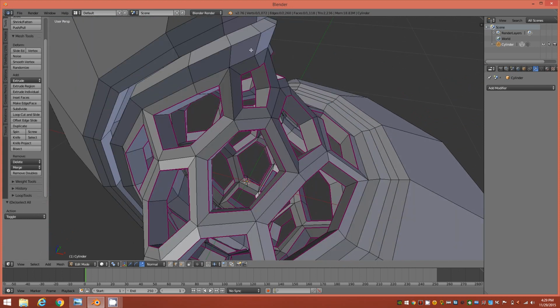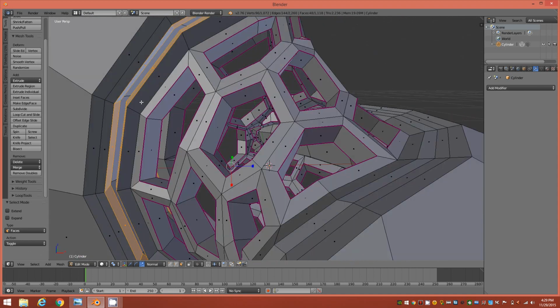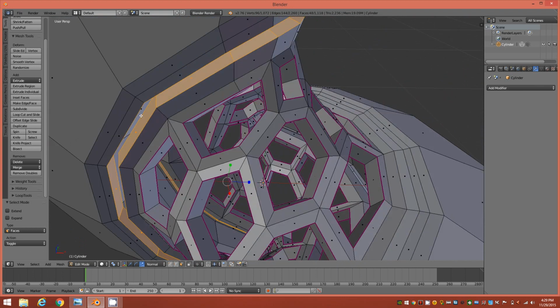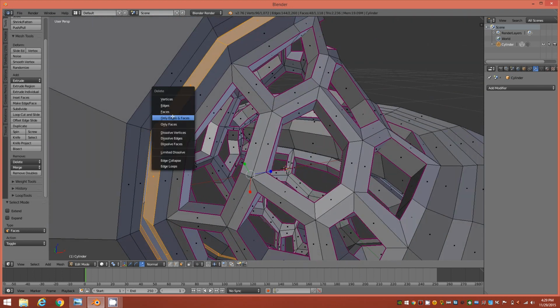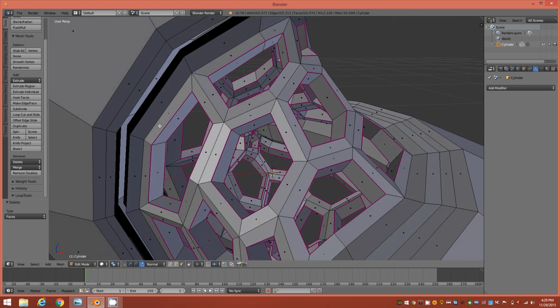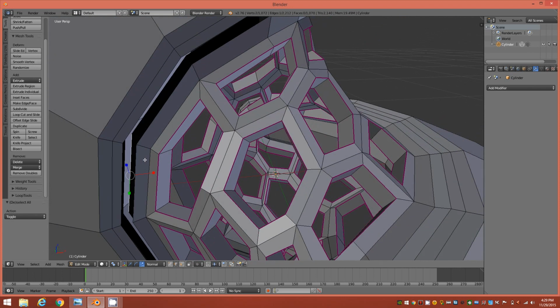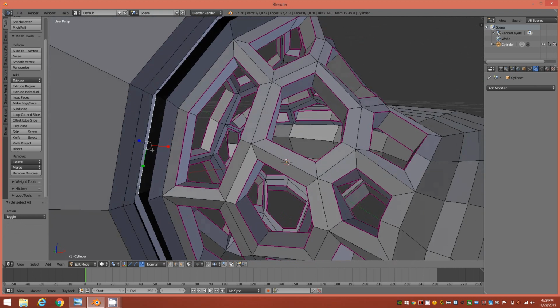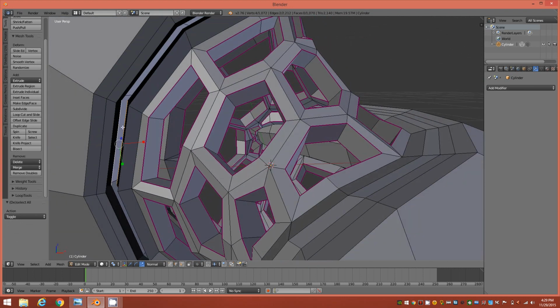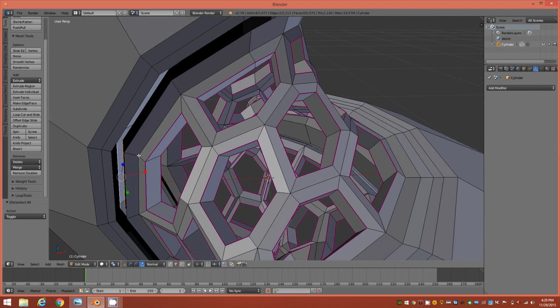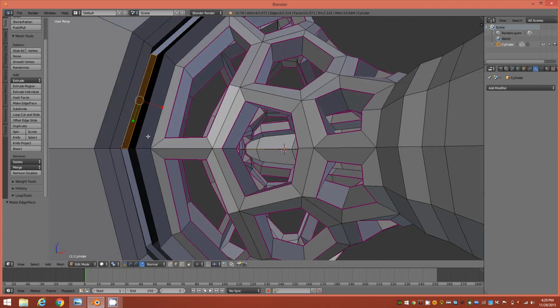And now we just got to do the same to this side. So go ahead into face mode and select that face loop, and then select that internal face loop on that object, so they're facing one another there. All right, and go ahead and remove those faces. All right, so now we've got to just select one edge. Let's go to edge mode. And we'll select one edge on the inside of the border that we just removed the faces, and then holding down shift, select the other one right across from it, and F to create a face there between the two.